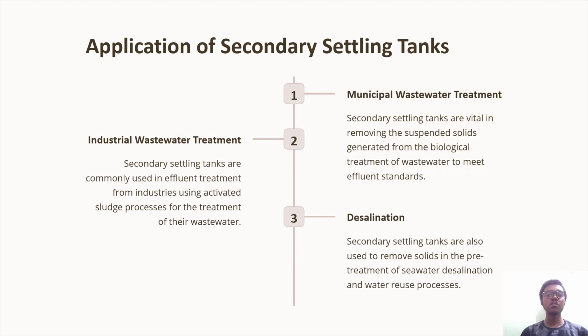Finally, the applications of secondary settling tanks: municipal waste treatment, industrial waste treatment, and finally desalination. First one, municipal waste treatment. These secondary settling tanks are vital in removing suspended solids generated from biological treatment of wastewater to meet the effluent standards. And the industrial wastewater treatment.